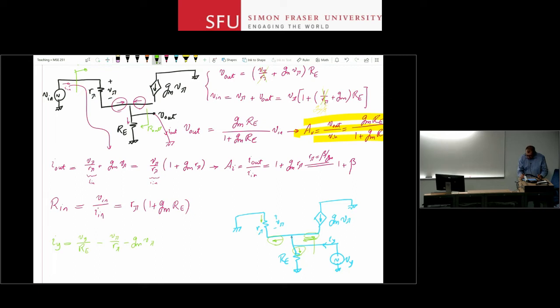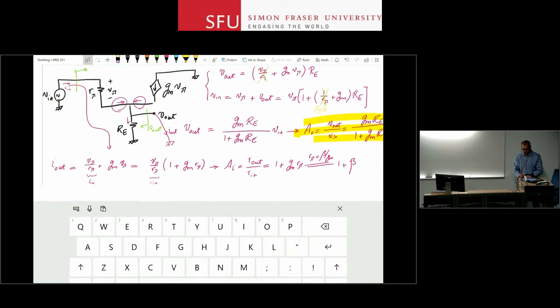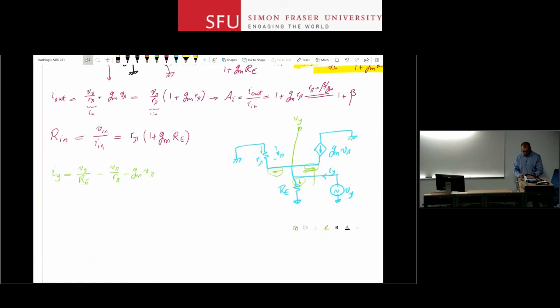I look at the voltage here. The voltage here is Vy. I'm directly connecting the source to that node, to the emitter of that device. Well, look at the circuit. V pi here is measured from base to emitter. Vy in this case is from emitter to ground.